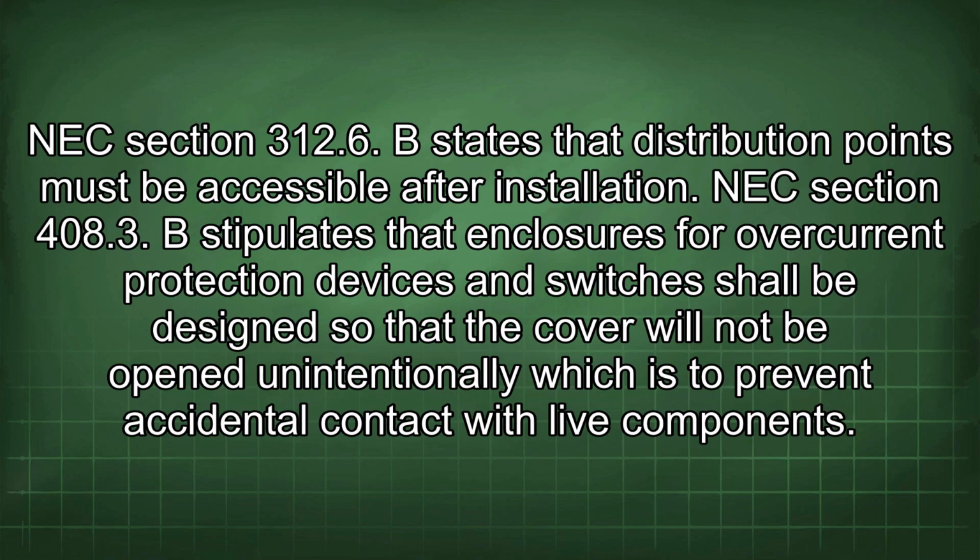NEC Section 312.6(B) states that distribution points must be accessible after installation. NEC Section 408.3(B) stipulates that enclosures for overcurrent protection devices and switches shall be designed so that the cover will not be opened unintentionally, which is to prevent accidental contact with live components.